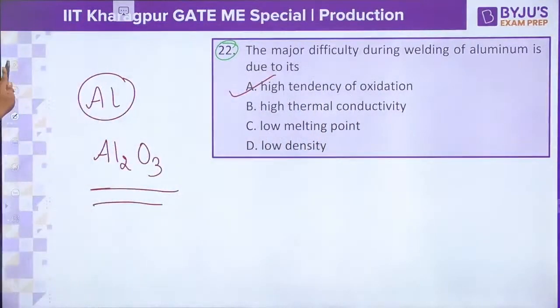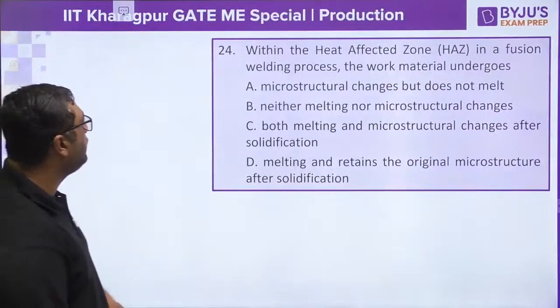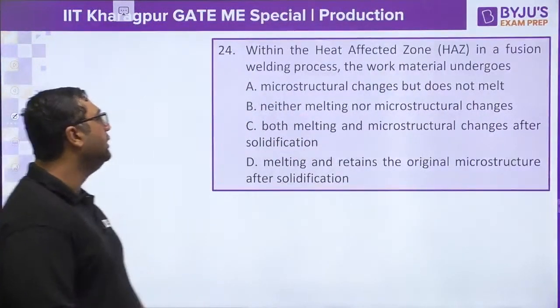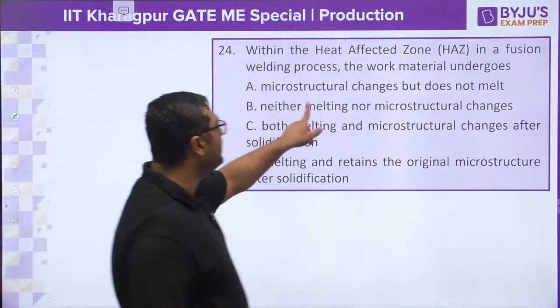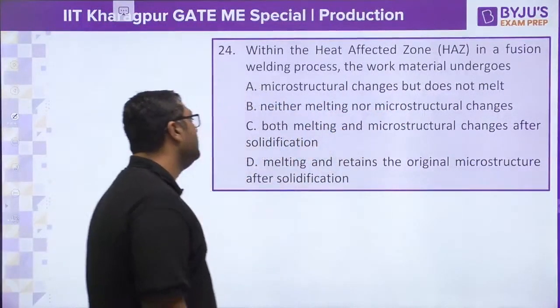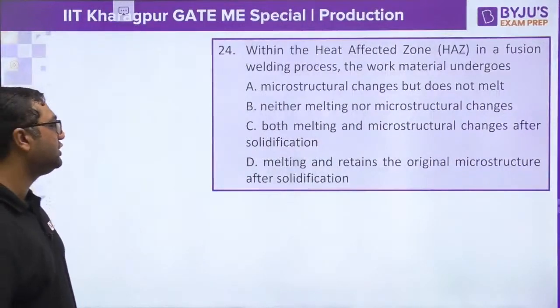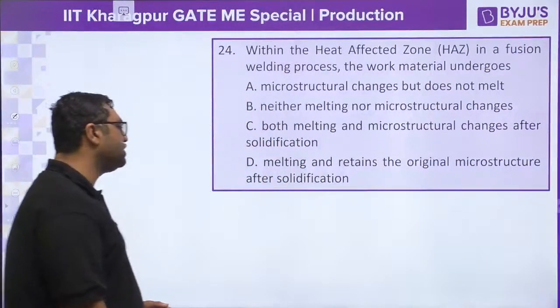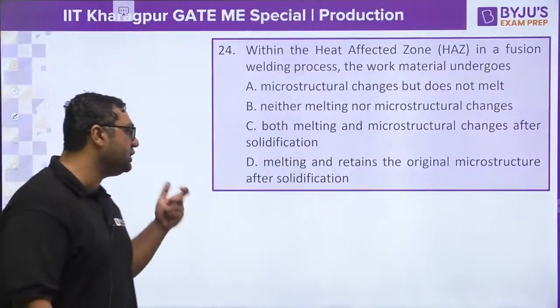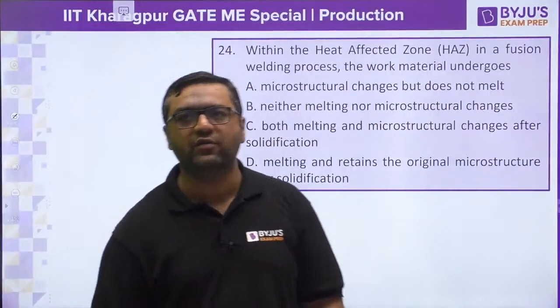Okay, yes. Next question. Question number 24. Within the heat affected zone, in a fusion welding process, the work material undergoes microstructural changes but does not melt; neither melting nor microstructural changes; both melting and microstructural changes after solidification; or melting and retains the original microstructure after solidification.